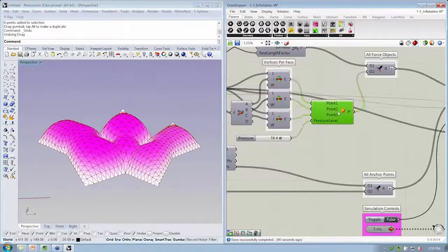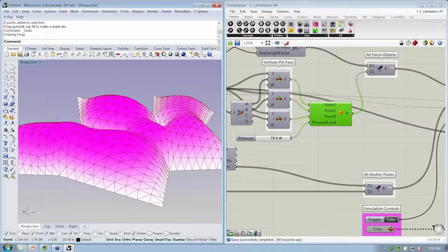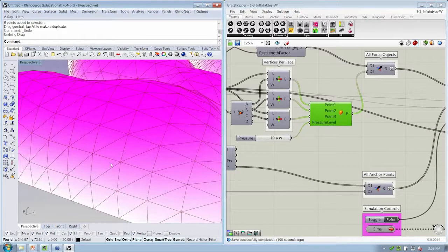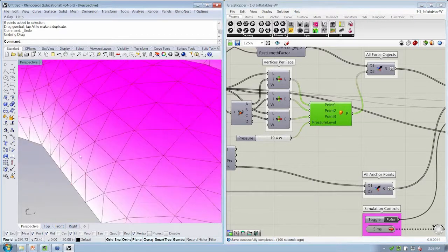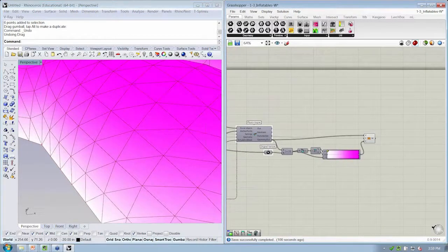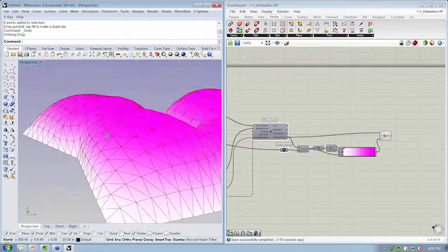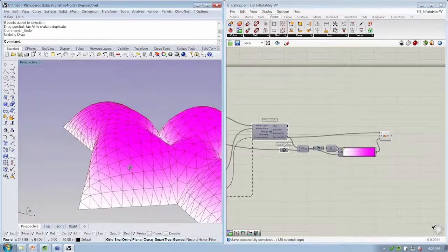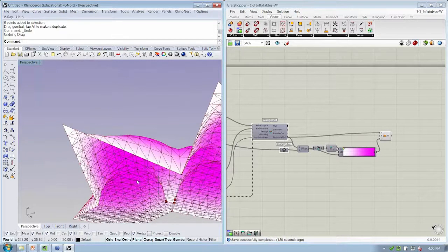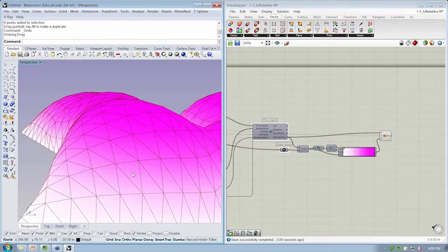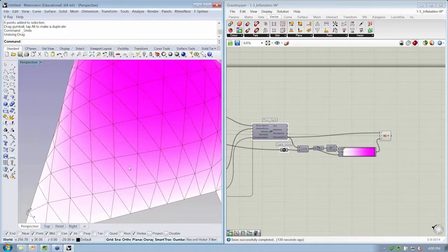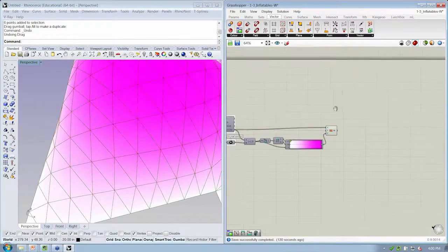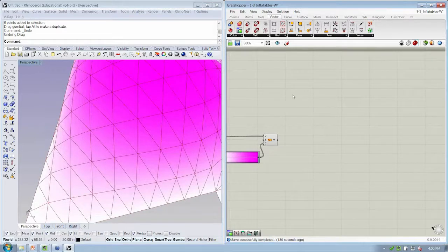There was a question about exactly how the pressure force is working. It is working perpendicular to the face of the mesh. So if you imagine that here at this mesh, I'll just draw this really quickly. At the center of the mesh, if there is a vector that is pushing on it, that's how the pressure is working. Of course, it changes as the simulation runs, from being essentially up everywhere at the initial state of the simulation to swinging around and moving perpendicular to the face at the current state. That's how any pressure system would work. Like when you blow up a balloon, the balloon is changing, but the pressure is still being applied perpendicular to the face.